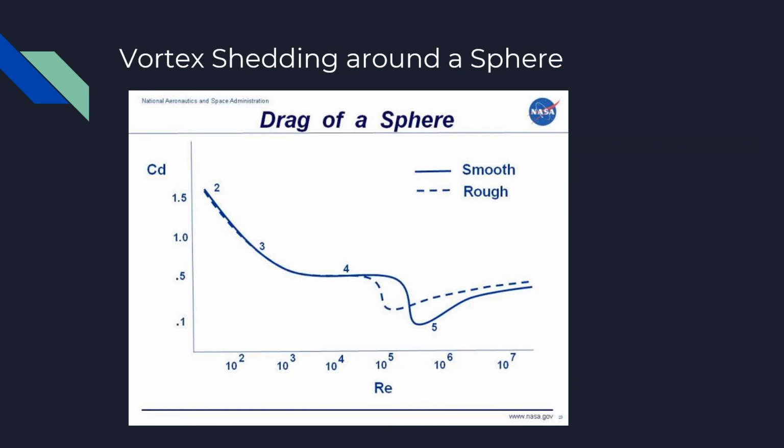The effect of a turbulent boundary layer applies in 3 dimensions as well as 2. Because of this, a sphere experiences high pressure and oscillating vortex shedding just like a cylinder. The difference is that vortices can be shed in any direction instead of in just 2.